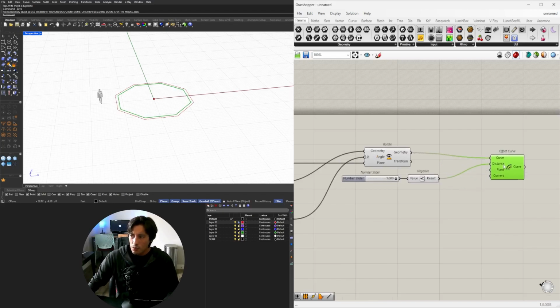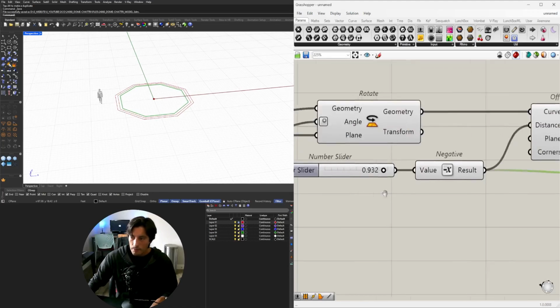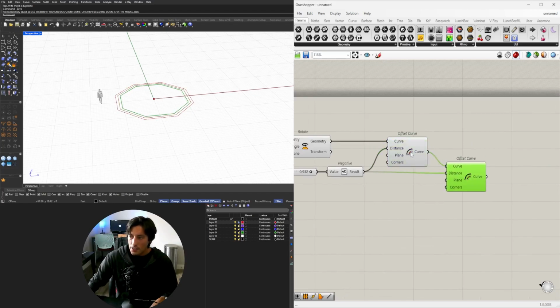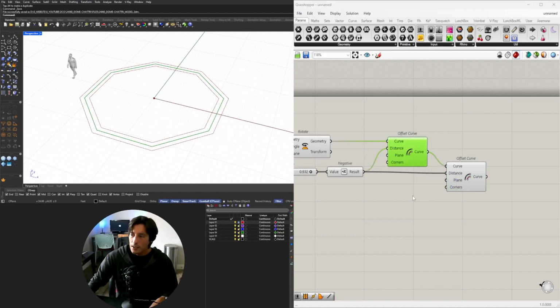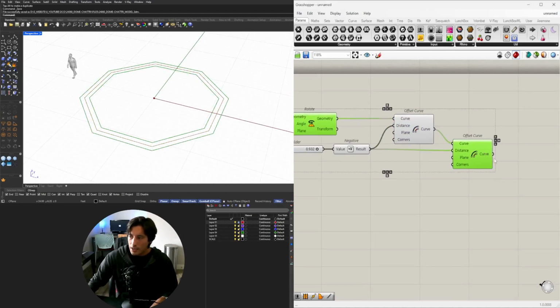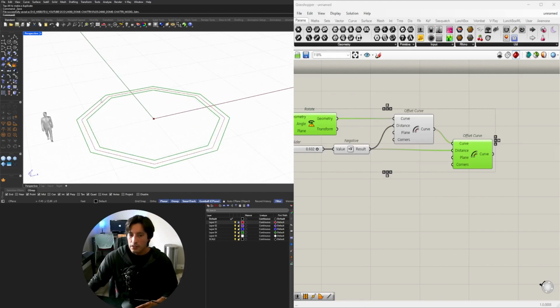And now if this is what I want to offset it again, now if you're only trying to do it twice, you can use this trick, which is just copy this and plug this one into this one, and it will offset this one again by the same amount. This way, this becomes your center line, and that's where your beams and your columns are located. And then the original and this one are going to become the outside face of beam, which would be the outside face of the shape of the design.